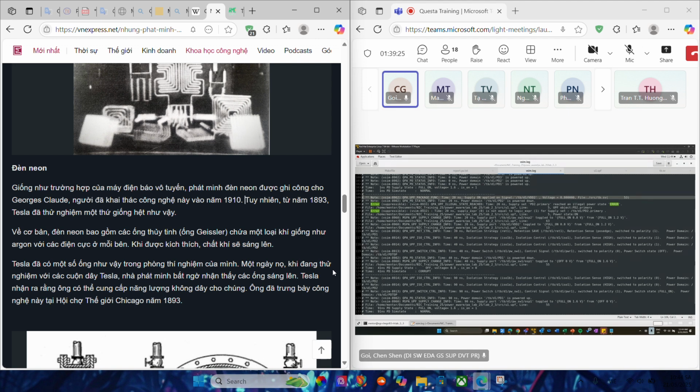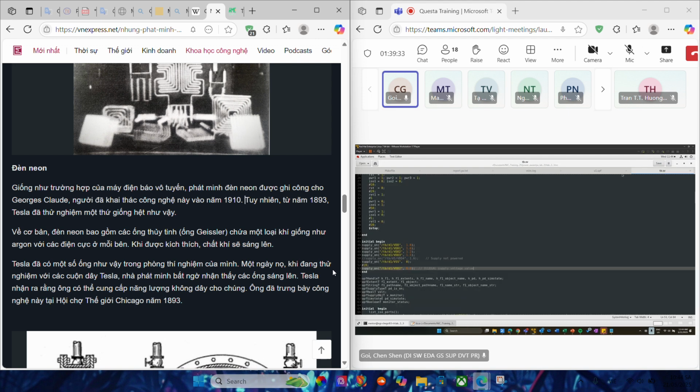So this is actually causing the error, and it directly gives you the line number 53 on test bench. So line number 53, the one that we fix. If we change this back to 1.2 as specified in the power state table, it will fix this error.